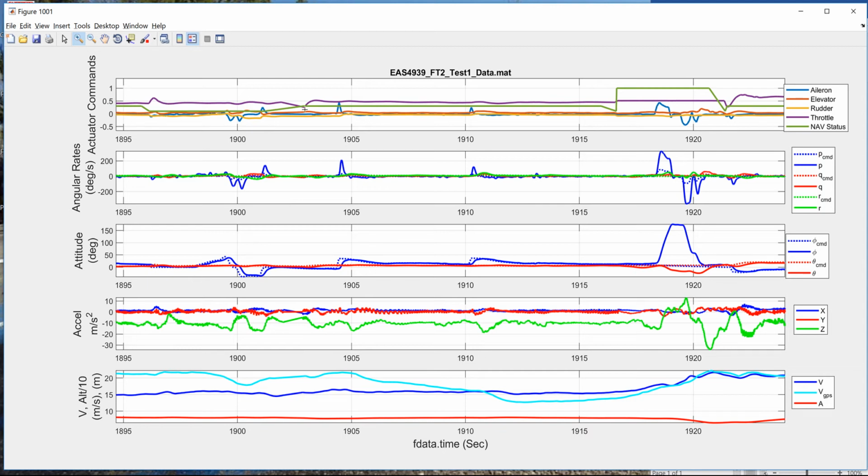If you see the dashed line move, that is an indication that the aircraft has attitude reference. So this green line here on the top chart goes down to 0.1, and this guy's moving, which shows the attitude reference. And then if it goes to navigation mode, it still has that attitude reference, but we're ignoring that, right? This is one doublet and another doublet approximately right here, which is the aircraft in a roll angle mode. This is where the aircraft rolled upside down, so it really wasn't a complete doublet, right? We only rolled one way and rolled right back up the other way, put it back into nav mode.